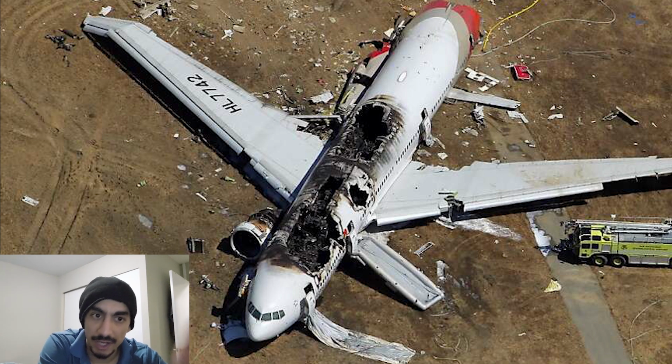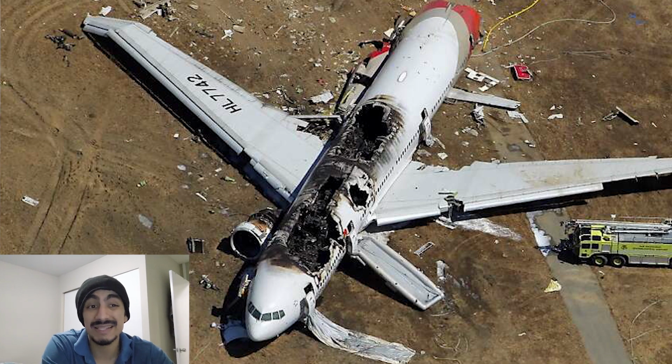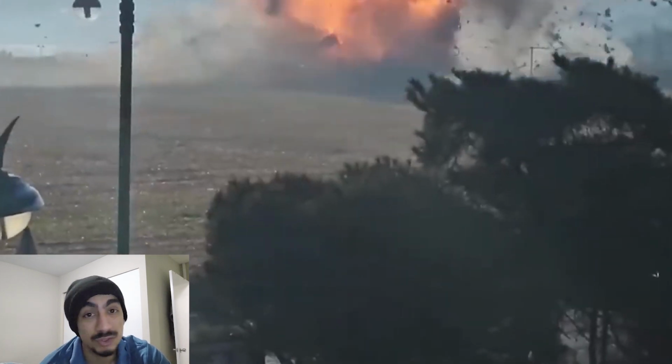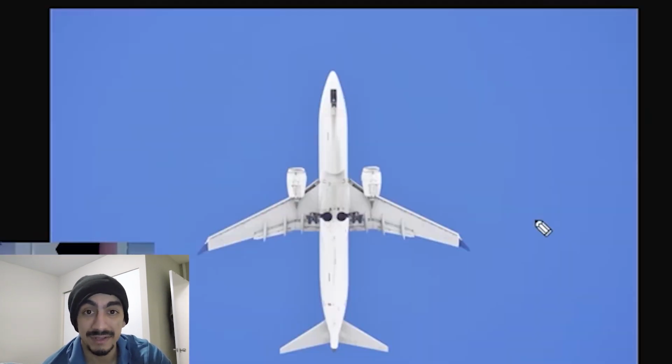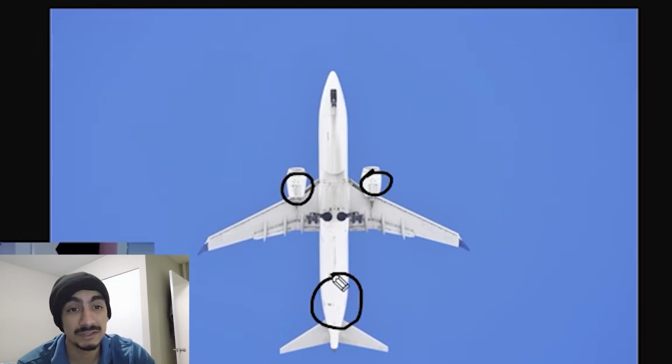Now in the Jeju Air 2216 crash, the aircraft did end up belly landing. So it was a belly landing situation, no gear, minimal or no flaps, and that is likely part of the reason that it skidded off the runway and slammed into a concrete wall, as you can see. So the plane just couldn't slow down, and the friction points were very minimal as well. It was the bottom tips of the two engines and a little part of the tail of the aircraft. So there was just not enough friction to slow down the airplane.